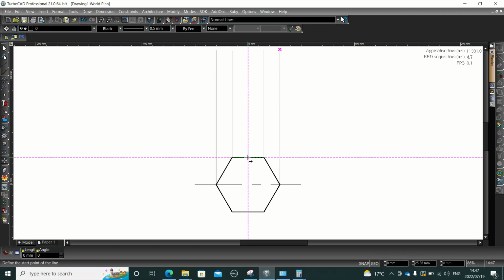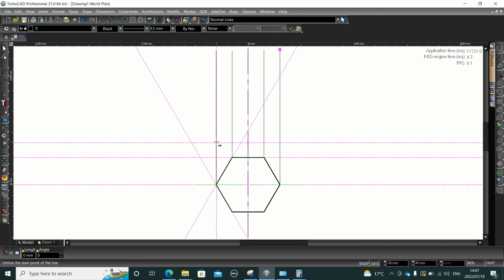If I position my mouse here, I will notice that my Y here is 26. If I round it off to a whole number, that is 26. So I need to add 20 on top of that 26, which means it will be 46, my Y. In terms of my X, I want my line to start from this line here. If I take a look there, I will see -30 if I position my mouse around this point. And again, make sure that the snap mode is on. It must not be this gray, it must be white. So as you see, my line will be x -30 and y will be 46.